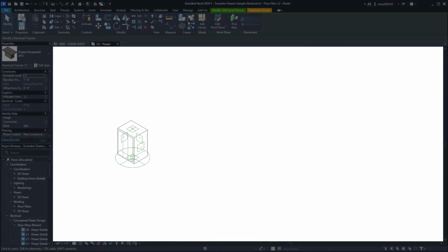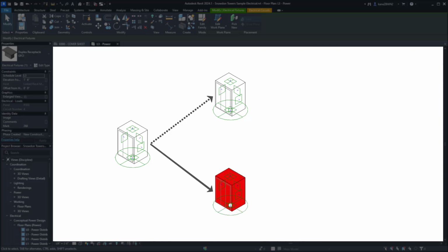Two, once you put an instance of that family in the model, the project stores that definition, that snapshot of what the family looked like in that moment. If someone has made changes to the file since then, it won't show up in this definition in your project. Also, you may want to make changes to this family, but only for this project. You can only do that if you are opening the project definition instead of the file. So, using Edit Family, make sure you're editing the family as it exists in this project.